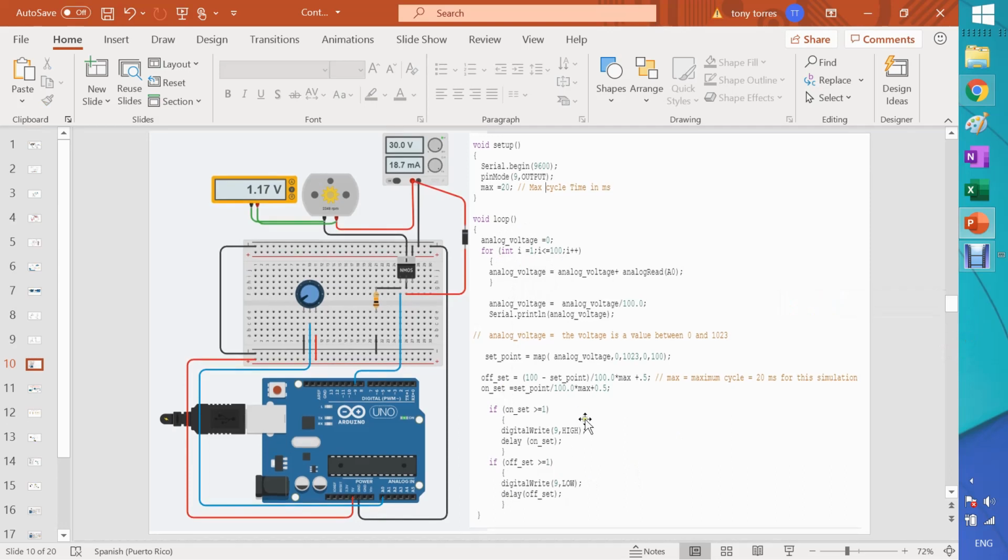You can do a lot of other stuff, obviously, up to a certain point, because if you distract the Arduino too much from doing the motor control, then again you will lose some of that ability to properly control the DC motor by adjusting the duty cycle within the maximum time of the 20 milliseconds. But this is 100% better than using the analogWrite from the Arduino. All right, let's see how this works right now within the Tinkercad simulation.